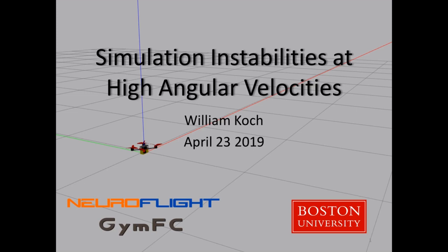Now, during development of our higher fidelity quadcopter model that more accurately reflects the aircraft that we're transferring our trained neural network to and compiling it into NeuroFlight, we observed some simulation instabilities that would occur at high angular velocity.